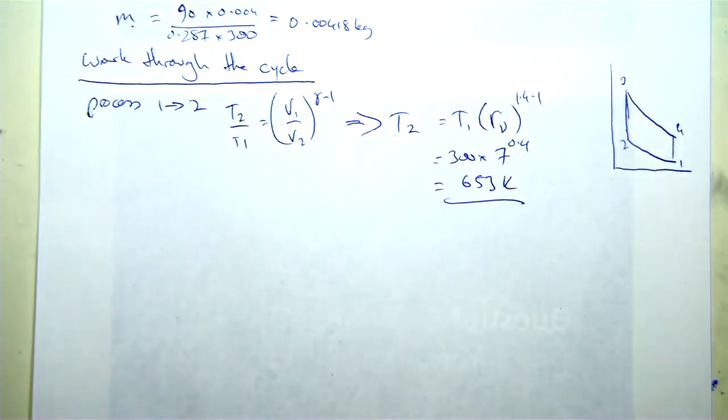The reason why I'm not chasing after any extra stuff is on an ideal gas process, a lot of the energy transfers that I want to calculate can be solved with delta T. Internal energy can be solved with CV delta T, enthalpy can be solved with Cp delta T. So for the moment, just finding the temperatures at each corner will be enough for me to solve energy transfer problems. On an adiabatic process, where I've got no heat transfer, I've just got work equals delta U.